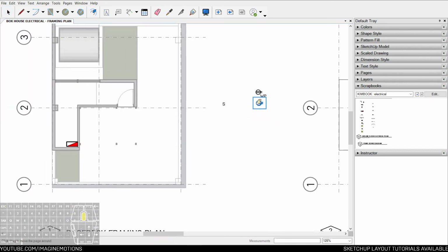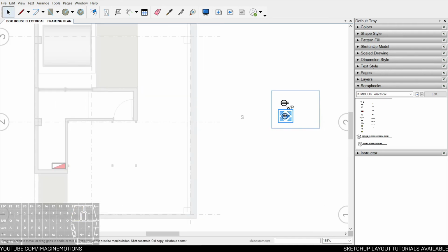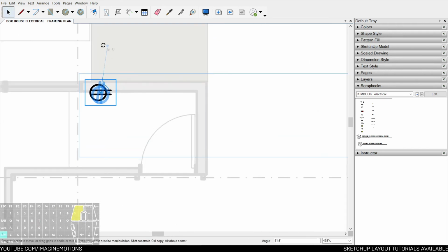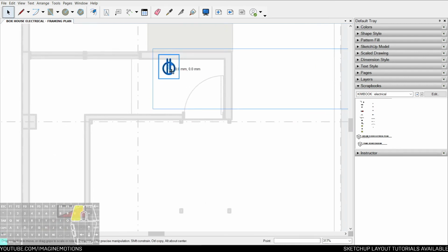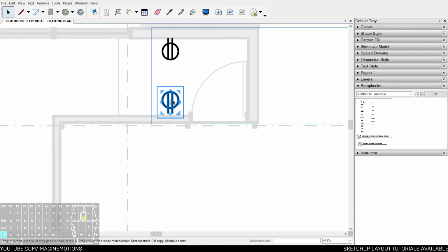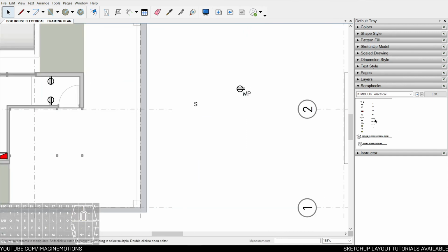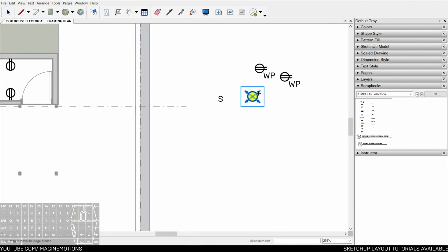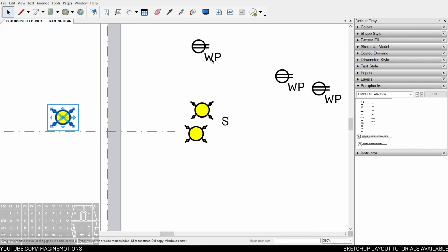So if you're going to lay this out, for example, you group them together. You could just rotate them, hold Shift, 90 degrees. Control to copy and Shift R to flip top and bottom. No problem as well. So these scrapbooks are included in your volume. This can be your pendant light or chandelier, whatever symbol you have. You can even customize your own symbol.